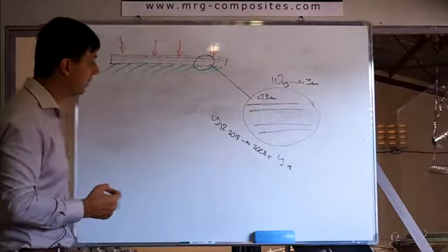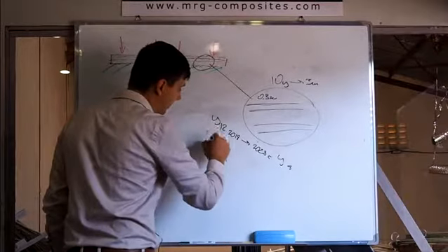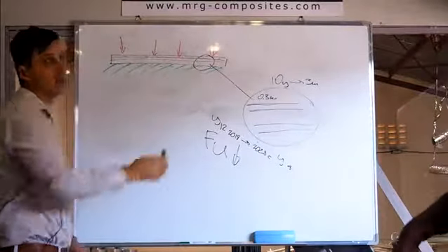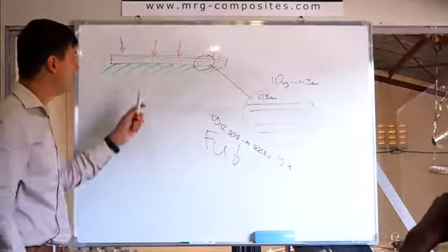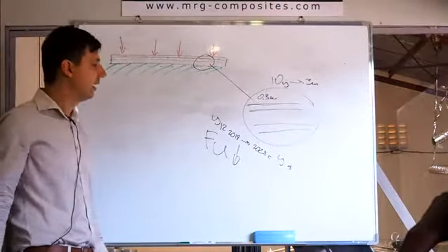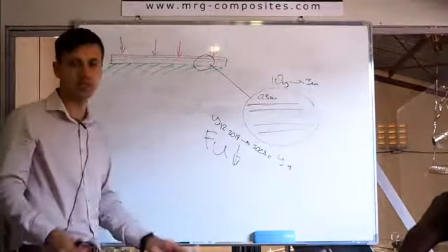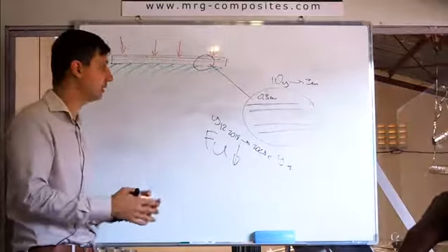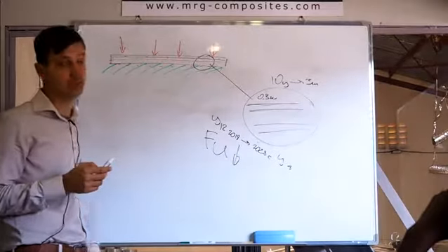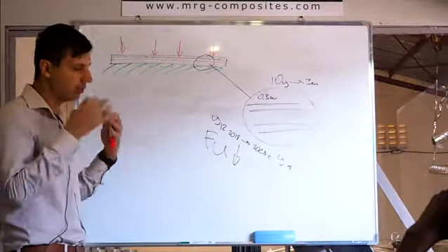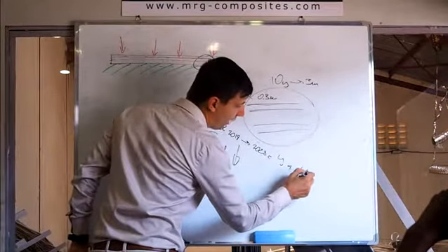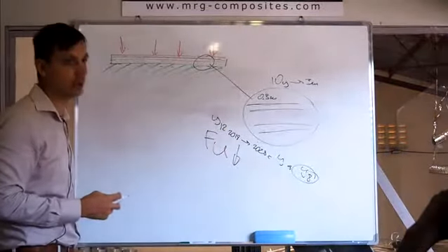Y9. And the problem is that ultimate stress becomes less. But guys, forces are still the same. Gravity is still here, and we don't want this structure destroyed after only 10 years, because construction is pretty expensive. Always we calculate for 25 years, sometimes more. So engineers know the minimum ultimate stress they have to handle; let's say all of these bars should be Y8. It's enough to hold the stress.